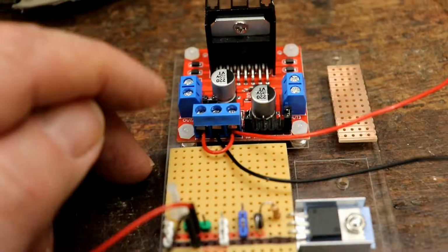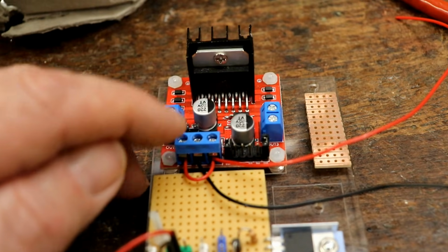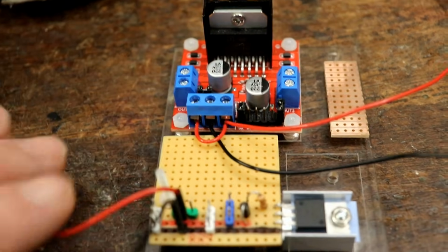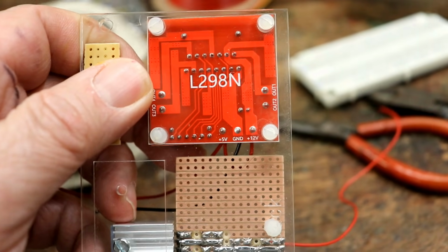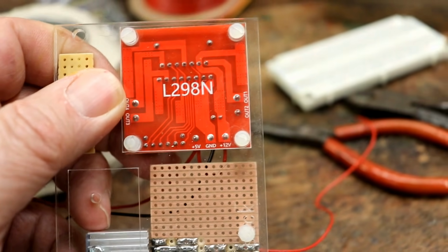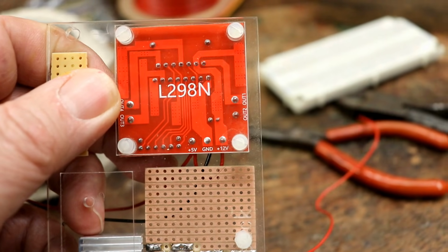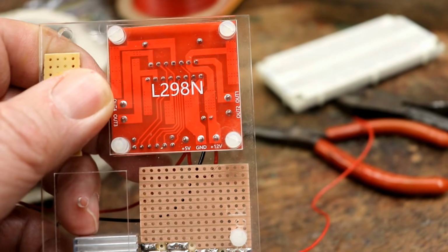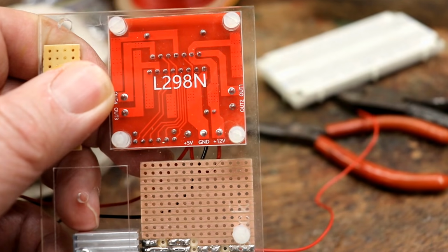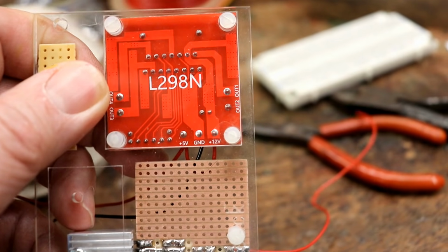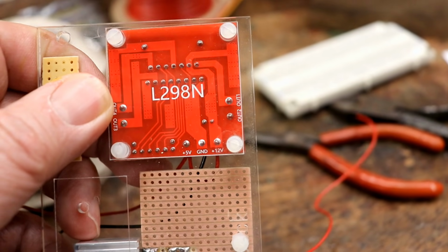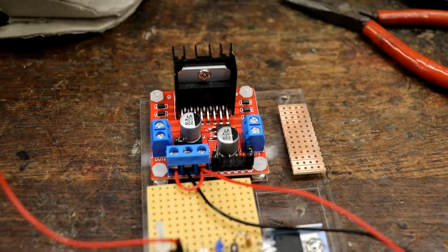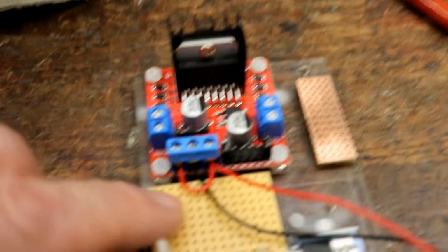When you wire up this sort of H-bridge interface, there are two connections for positive volts. The one on the right is plus 12 volts because you can run 12 volt motors using these interfaces, or any voltage below that. And there's also a plus 5 volts, which is to run the logic on the actual chip itself, with ground in the middle. So because we want to run all of it off 5 volts,